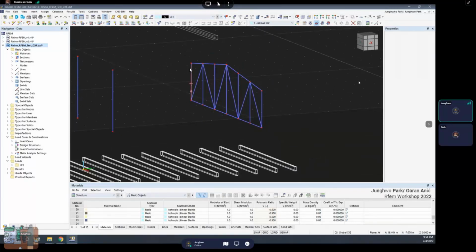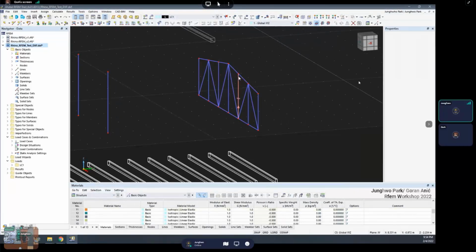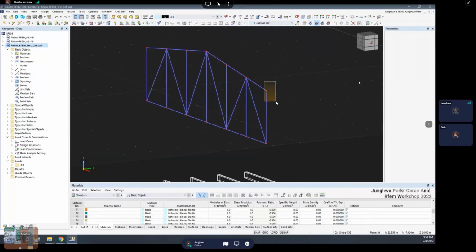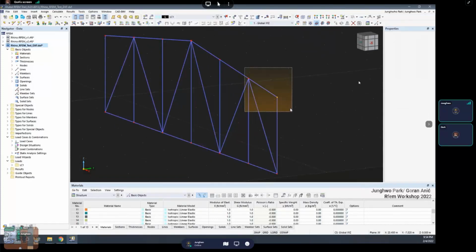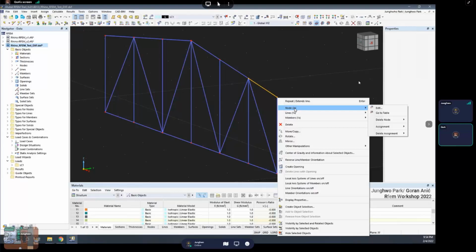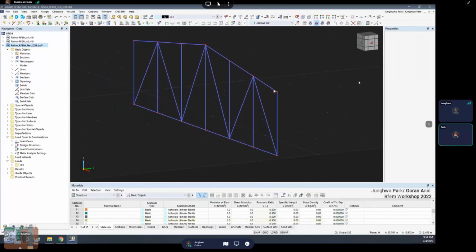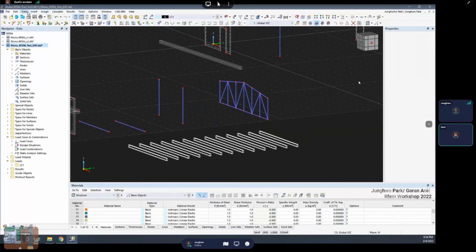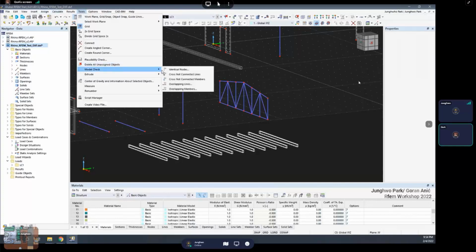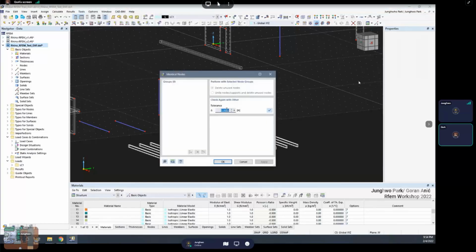But in this case with nodes, when you manually move them with the mouse, how do you know they are completely connected? When you select it, you see that here's just one node. For example, if I select it more, here two nodes stay. Okay, two nodes, I see. So they are automatically connected. And I think we already mentioned that here are also tools for model check, which can check identical nodes if they are really close to each other. You see, we don't have it.